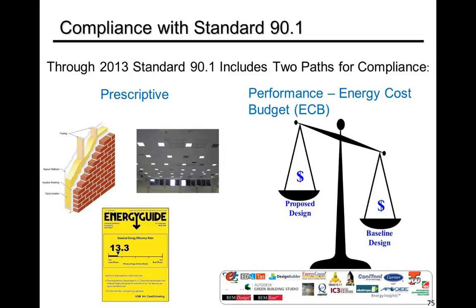Using that methodology, you simulate a proposed building design and compare that to a baseline building design. And if the proposed building design has a lower energy cost than the baseline building design, the project complies. We do that using simulation tools like DOE-2, EnergyPlus, eQuest, TRACE, etc.